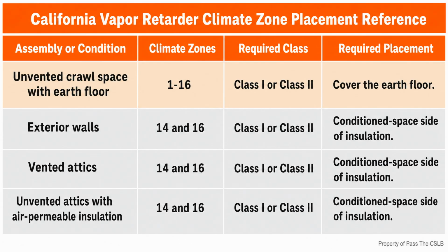On the exterior wall, the water-resistive barrier manages rain rather than interior vapor diffusion. The California Residential Code rule in the research uses at least number 15 asphalt felt, or an approved equivalent. It is applied horizontally with the upper layer lapping over the lower layer by at least 2 inches. Vertical joints lap at least 6 inches. The direction is as important as the dimension.